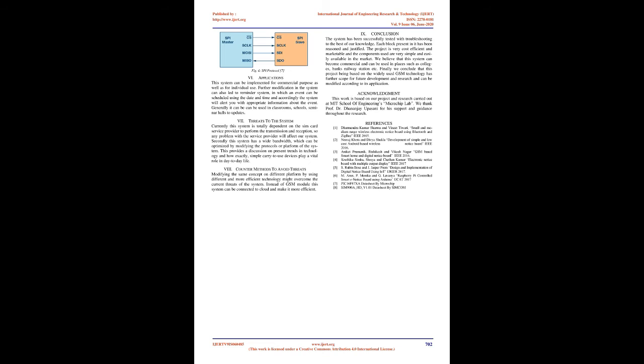PIC16F877A microcontroller. 7. Programming the PIC microcontroller. A PIC microcontroller can be programmed with different software that is available in the market. There are people who still use assembly language to program PIC MCUs. However, most programmers use embedded C language to program the microcontroller, because of its easy-to-read nature and code optimization using functions and header files.